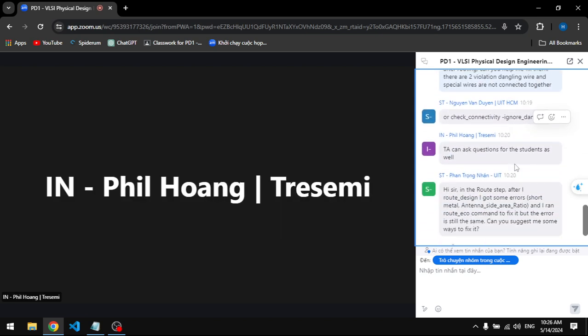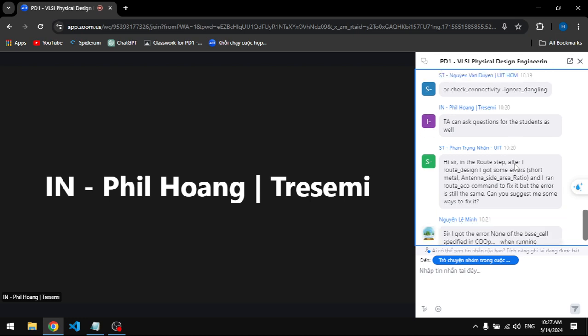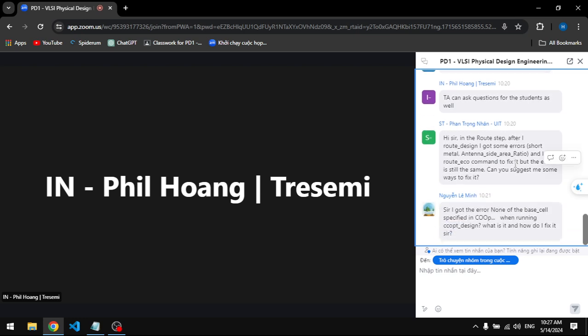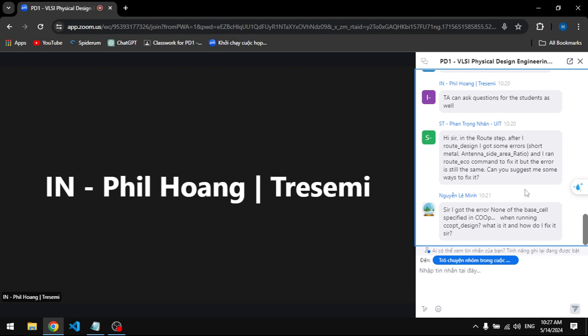One comment about insertion delay target is that usually you don't really know how to put that constraint. But in case you have latency, you need to do certain manipulation of the clock nets going to a memory, for instance, then you control the latency. Otherwise, the skew will determine the latency, unless the latency is too long.